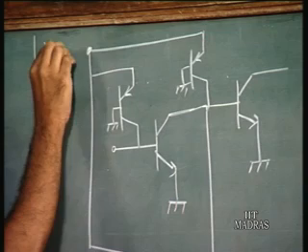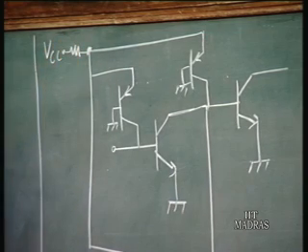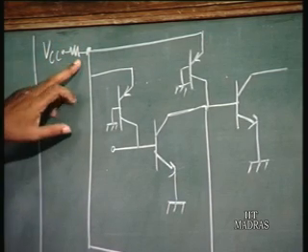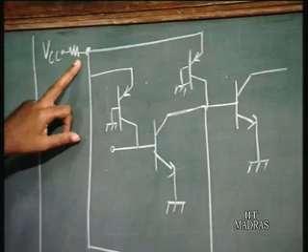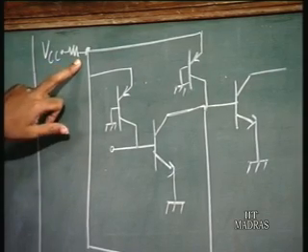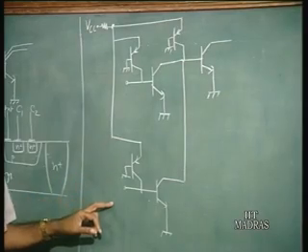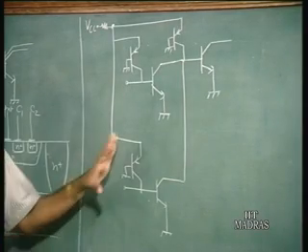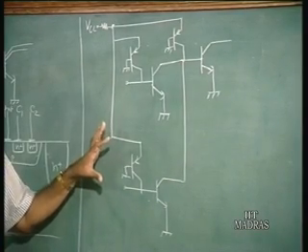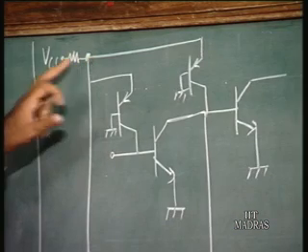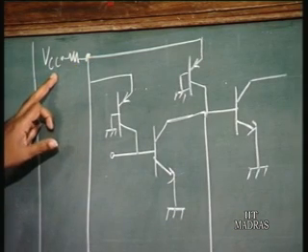VCC through a resistance. So usually, as I said, this resistance which you have here is usually external to the chip, you don't require a resistance inside. So if this is an I squared L circuit, you don't require a resistance as such. So if this point is made available, you can connect through VCC through a resistance.